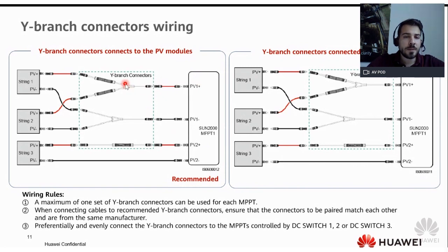Also, fuses are in general manufactured with certain tolerances, and they don't tolerate heat well. So it is actually a good thing that the fuses are not inside the PV inverter, because the inverter also emits heat, so there is no heat disturbance for the fuses. They are outside, so their temperature will be more even, it will not affect the production, and there will be no problem.